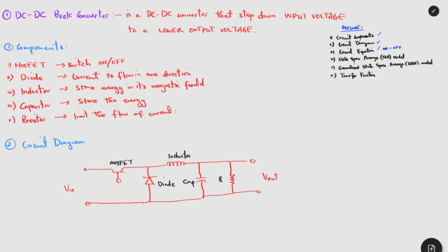The important thing to realize is that the control signal, as we have mentioned, which is the duty cycle, will now be able to produce a PWM signal. The MOSFET is now going to operate on a PWM signal. And because of this PWM signal, it will control the voltage output to be less than the voltage input.